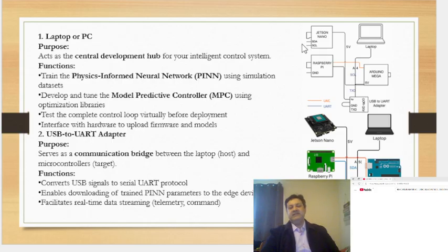And the TXT UART output, right here, is the UART output TXT line to the USB to UART adapter. So this is our other adapter, which is here, and the output transmits serial data, for example real-time predictions and voltage thresholds, to the laptop. That will go here.